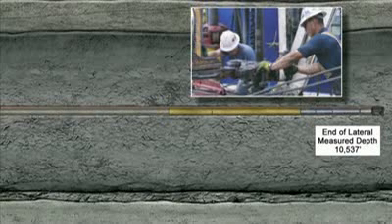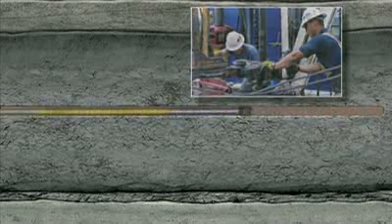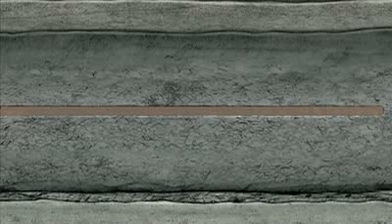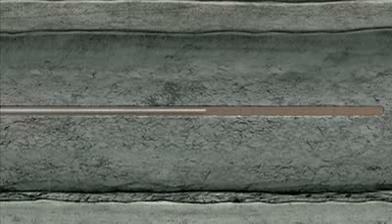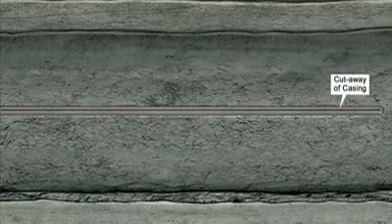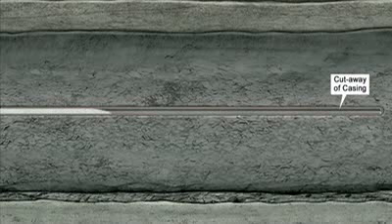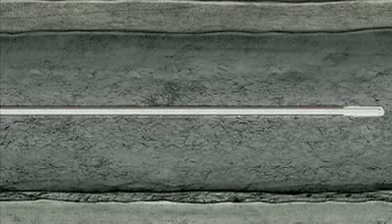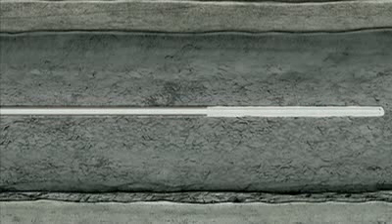Once the well has reached the desired depth and location, the drill bit is removed from the wellbore one last time. A completion well casing is inserted along the full length of the wellbore. Cement is once again pumped down the well and forced up between the casing and wall of the hole. This process permanently secures the wellbore and prevents hydrocarbons and other fluids from seeping out from the surrounding rock formations into the well. The drilling rig is now no longer needed and can be removed from the site. A wellhead is placed on the surface, connecting the top of the well.